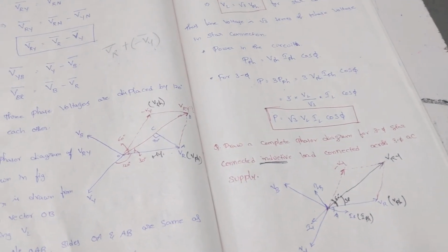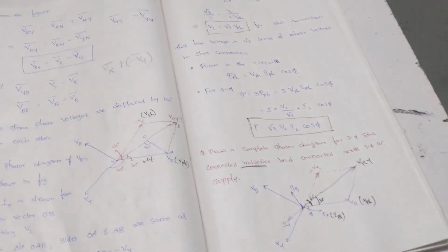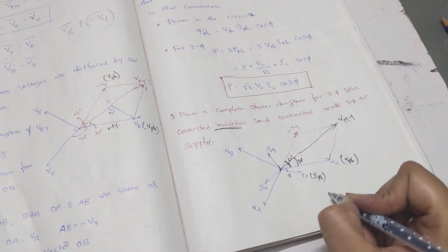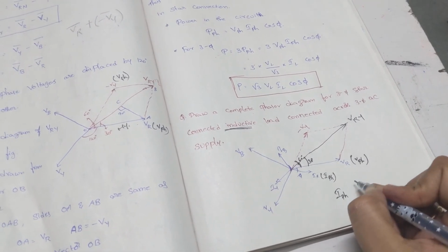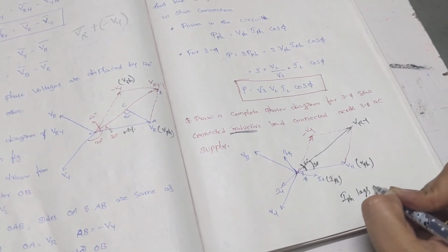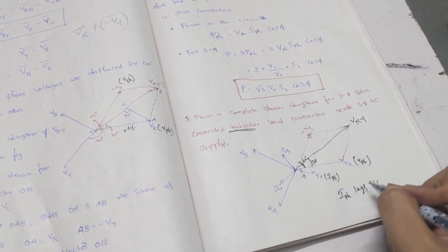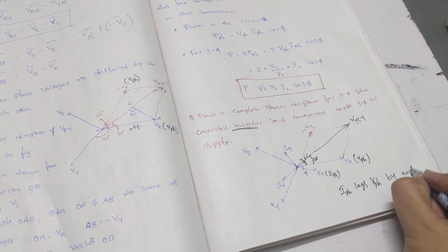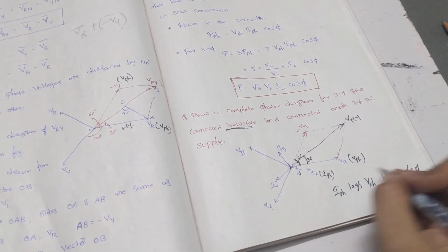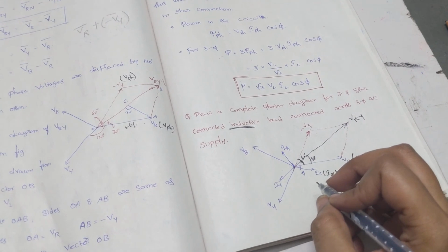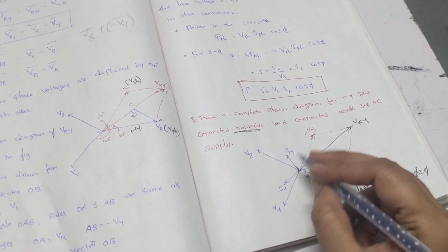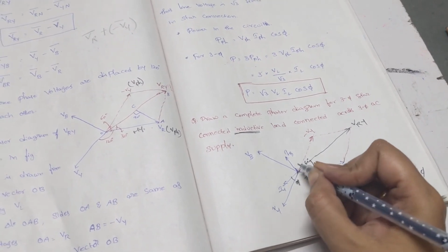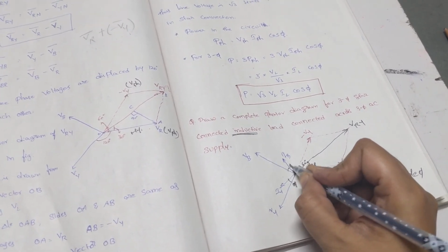With this we can draw some conclusions. Whatever the phase current, I phase lags the V phasor, that means the phase voltage, by an angle of phi in each and every phase. So in every phase it is a lagging, inductive load.